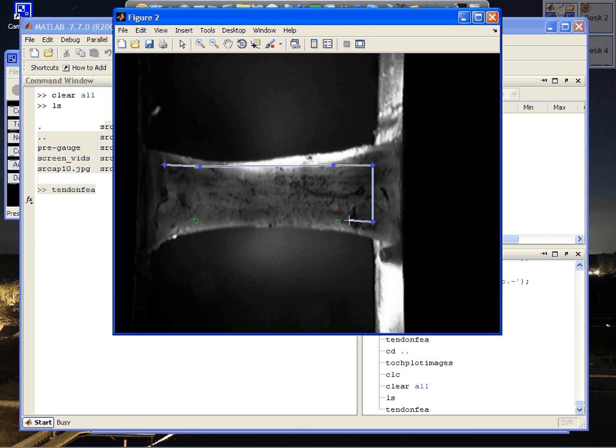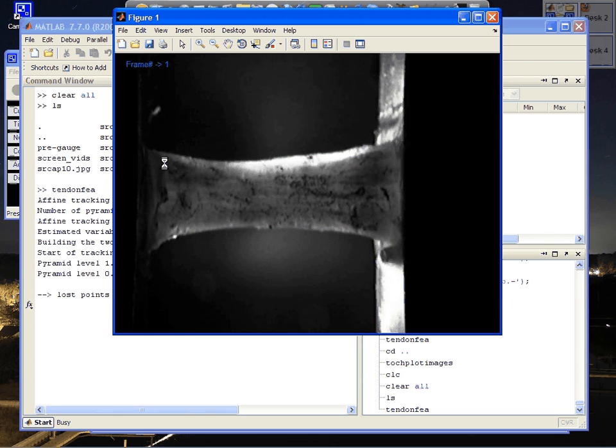And now, once again, I move my cursor to the inside of the circle, select another point, and then the inside of the next circle, and finally we're going to close this off. I'm going to select this point, and now I'm going to double click to finalize, and you'll see the mesh appear. Okay, there's the mesh, and you see there's 3 regions that are formed. You have to be specific about how you do that in order to generate your 3 regions.